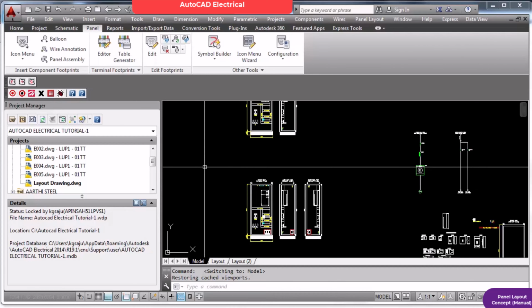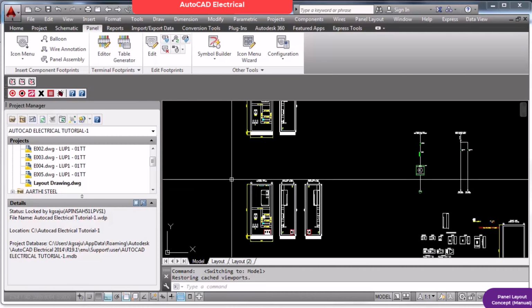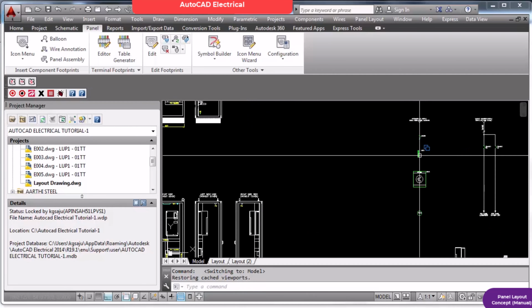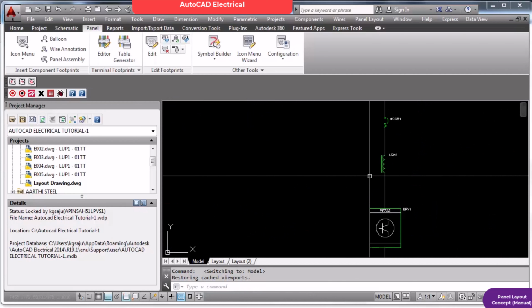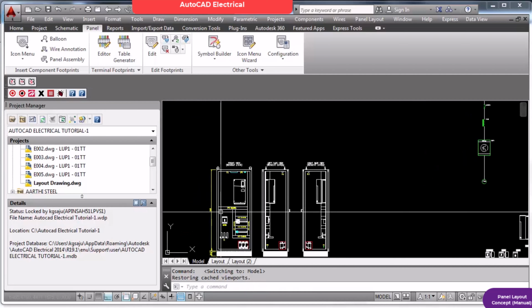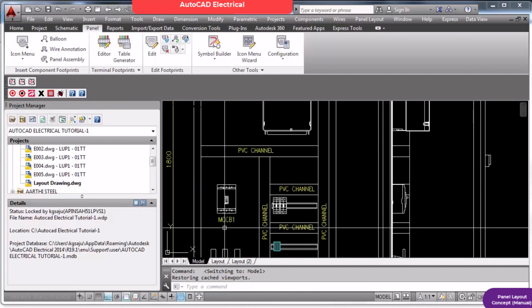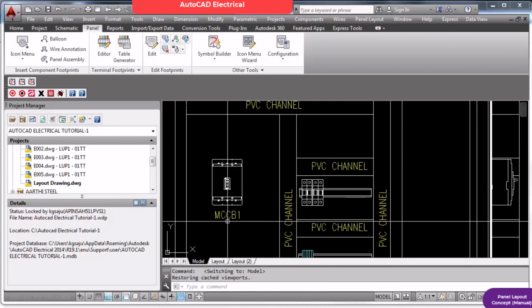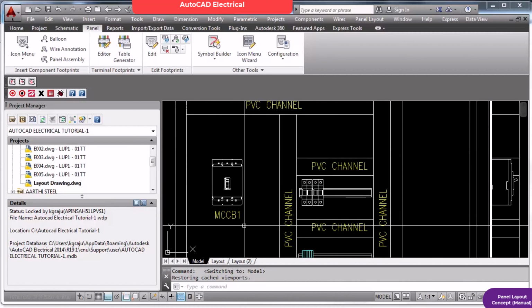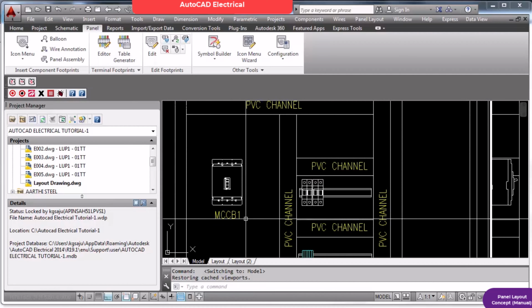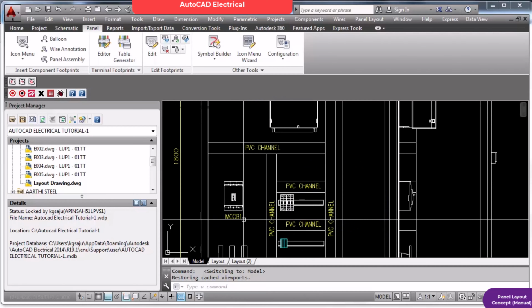But as we are learning AutoCAD Electrical, we should learn how to make layout drawings using AutoCAD Electrical. So this tab stands for that. It has many features. You can interlink, you can go to the schematic, you can copy things from there. Once you delete a few things here, that will automatically update. Now you see, if I delete something from this schematic of this particular wiring, I have to come back to this sheet. If I replace the MCCB in the schematic with the MCB or SFU, first I have to do it